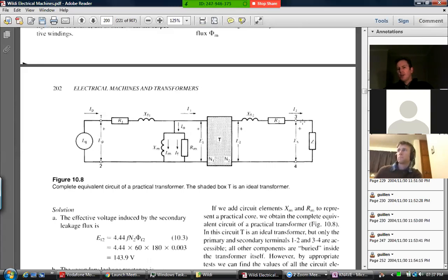And here's the load. So the transformer is everything inside this box, from the terminals onto the transformer there, and those two are the terminals at the end of the transformer. The transformer is everything in that box. But inside there are these various circuit parameters, and an ideal transformer sits inside there because it's a box with a T and a turns ratio.